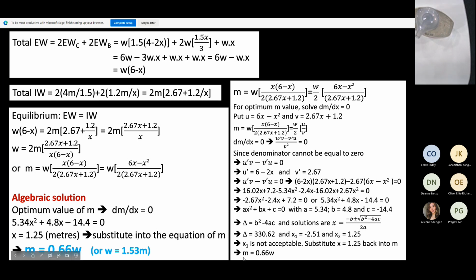So you use Eurocode, it will give you the moment M, and then you can get the critical load W that will make the slab fail. And that concludes this problem. You can see that we started with the slab where the x values were unknown, so we had no idea where the yield line starts, and then we obtained the solution for that.